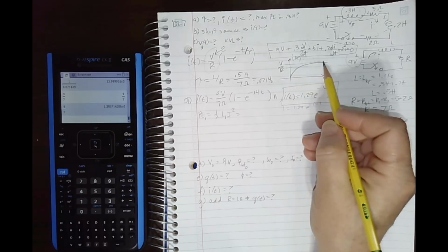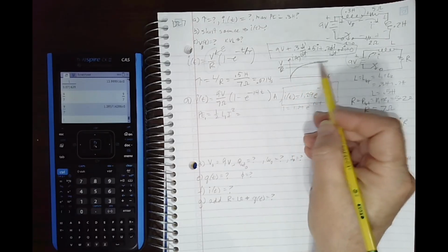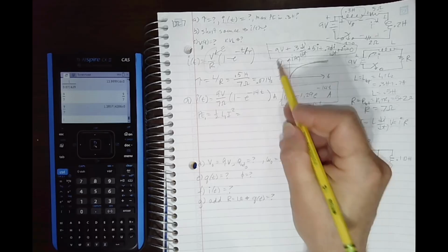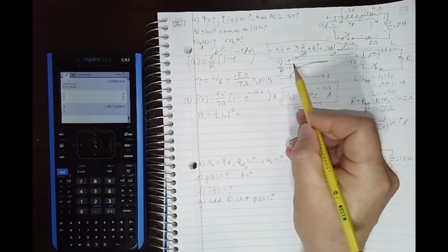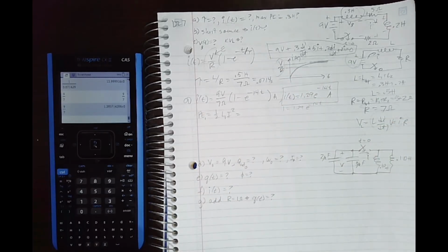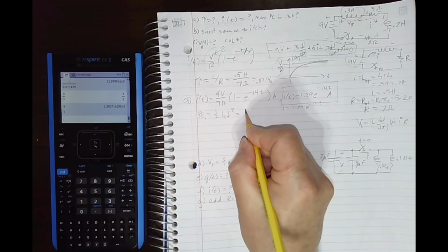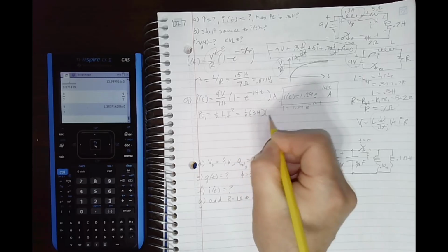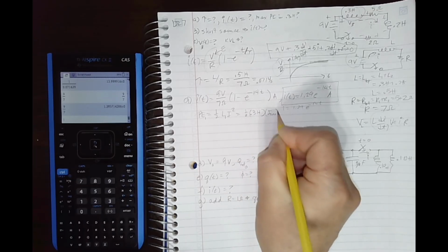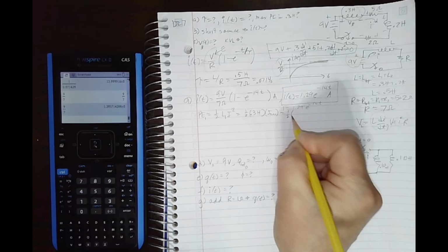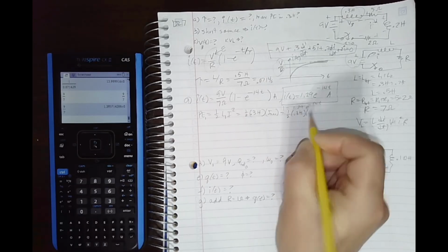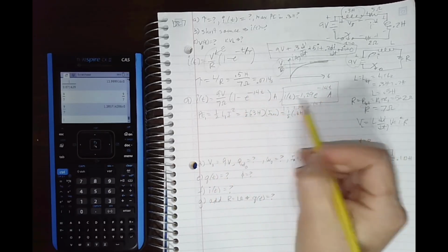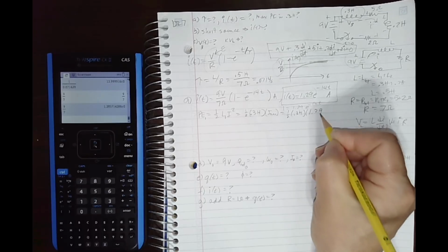All right, so like I said, when does the maximum happen? It happens when the maximum of this current happens, which is out here, right? So the maximum current is this limiting asymptote value here, which is V over R, right? So I max, 1/2 times 0.3 henries times the maximum current we just found here, which is the 1.29, right?